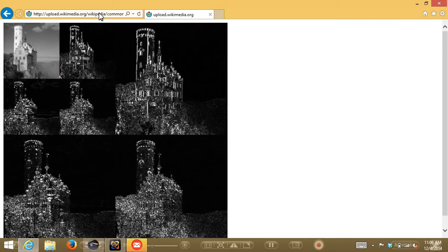Okay, so what you're seeing here is not really the best example, but this is a two-level wavelet transform. These are the edges that are most important at the highest level. This is what happens if I high-pass filter the signal twice, in both the vertical and horizontal direction. Then these are the high-pass edges that are most important at the original resolution in the left-right direction.